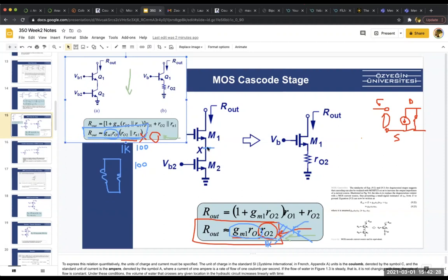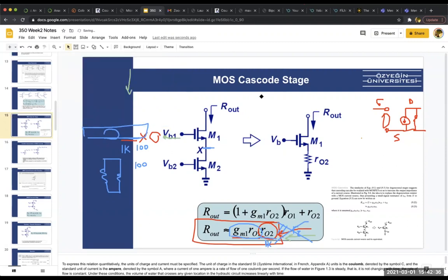And the reason is because in this middle node, in the CMOS, you don't really have that low impedance. Normally in BJT, you were seeing this R pi, but in CMOS, you don't have it. So this impedance is much higher. And if you look at the voltage at this node through an oscilloscope in the laboratory, you would see that this node has a much higher swing.